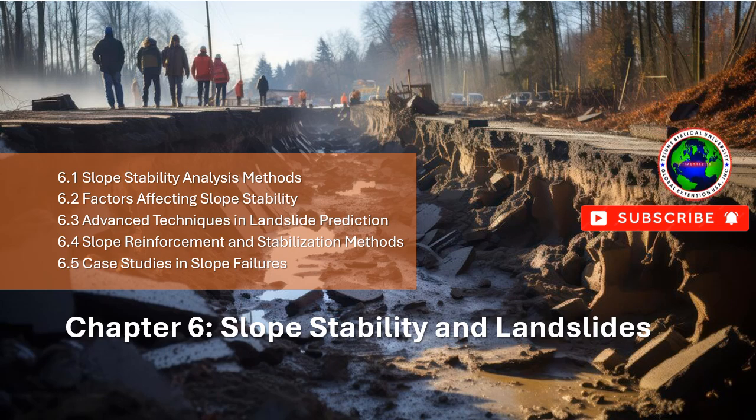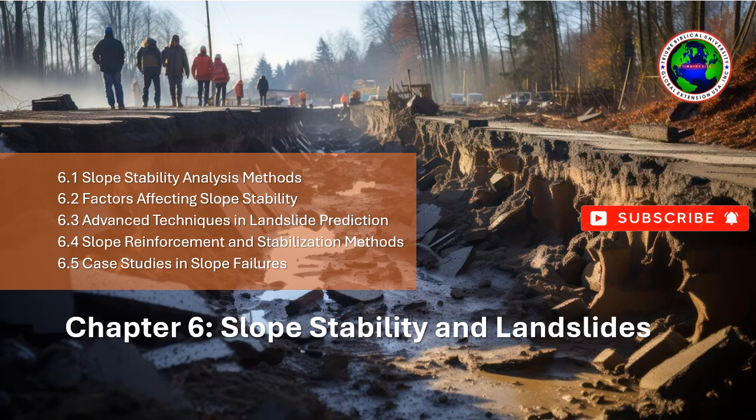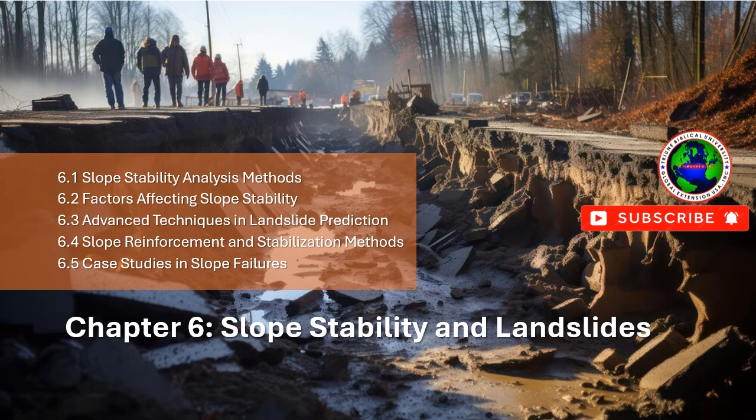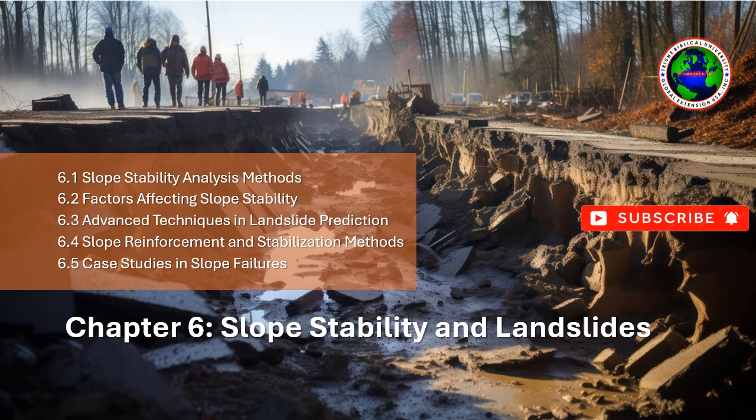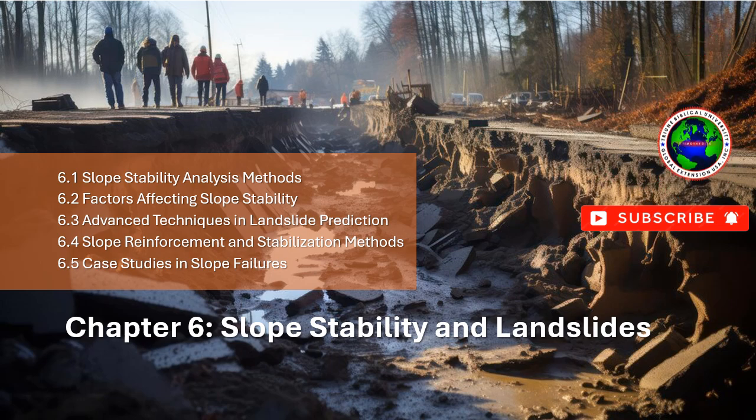Advantages: effective for stabilizing steep, rocky slopes prone to rockfalls or sliding. Provides a long-lasting solution with minimal impact on the environment. Can be combined with other methods like shotcrete or geogrids for added stability. Applications: stabilizing rocky hillsides, cliffs, and mountain roads. Used in mining operations and tunnels to prevent rockfall and ensure worker safety.